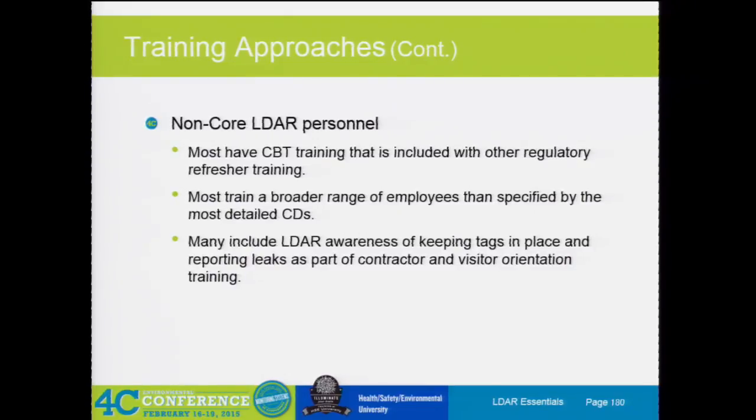And so by being able to put that type of information into why this is important for your non-core LDAR people, so operations, maintenance, hey, if you see a tag fall off or you have to pull one off because you're breaking this line and putting in some new equipment, please get it back to me. By the time you show some real data of, hey, by the time we hang one tag, you're looking at a good couple grand probably by the time it's all said and done, of just cost and all of this put together. That kind of helps them think a little bit more.